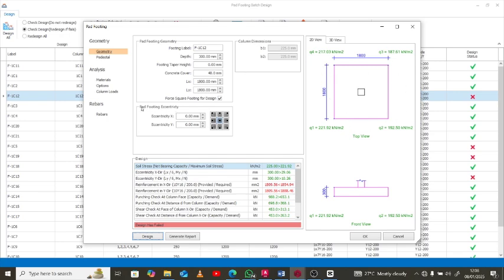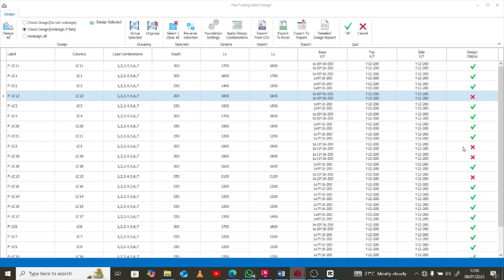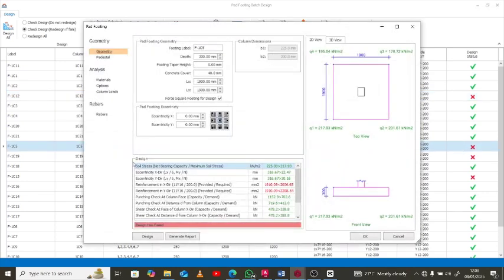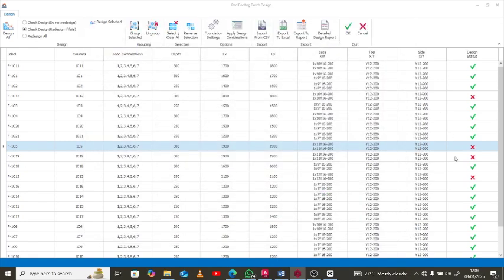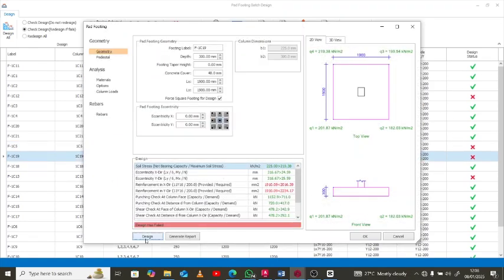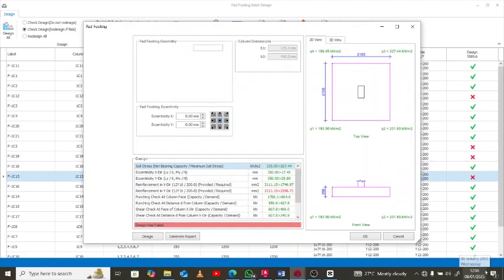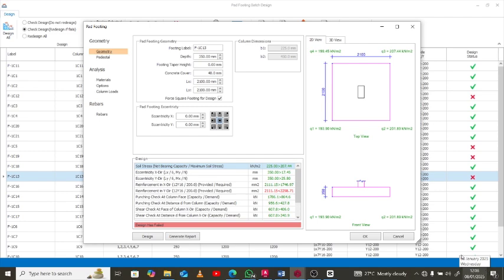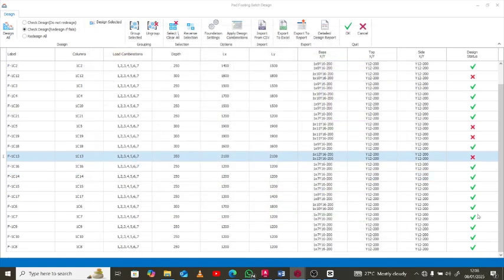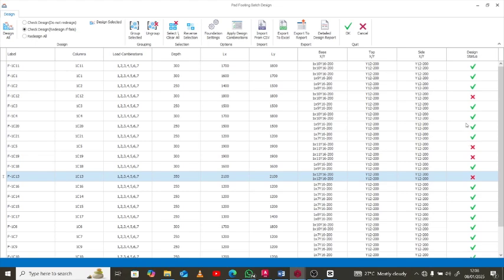That's massive. That's massive. The reinforcement is not sufficient. Punching is not sufficient. We may need to check this particular column base to see what's going on. All right, let's see for this 1.9. This is also massive. Wow, 1.9 massive. We may need to take a critical look at this individual column base. 2.1, and it still did not pass. So these are column bases that will require an extra look.